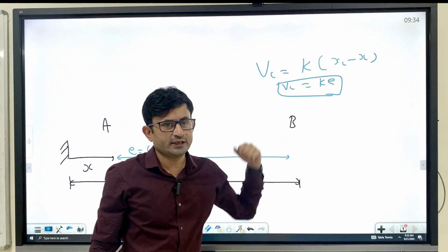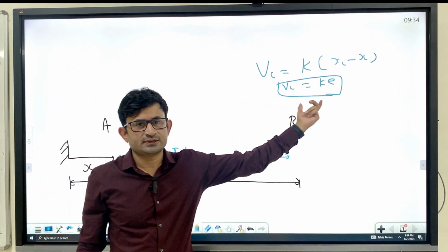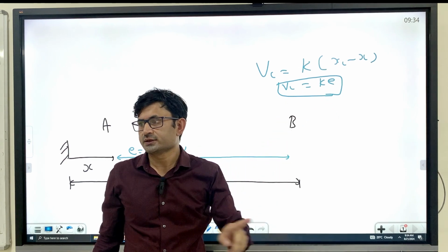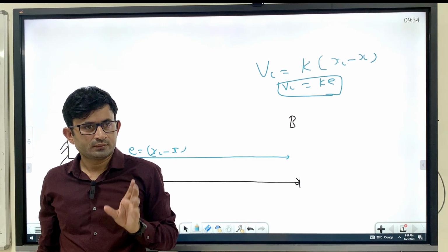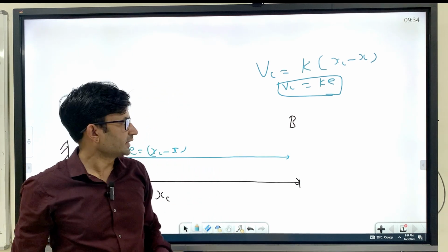If you reduce k, you move slower. This case, which is directly associated with the error only, is called the proportional term, generally called Kp.